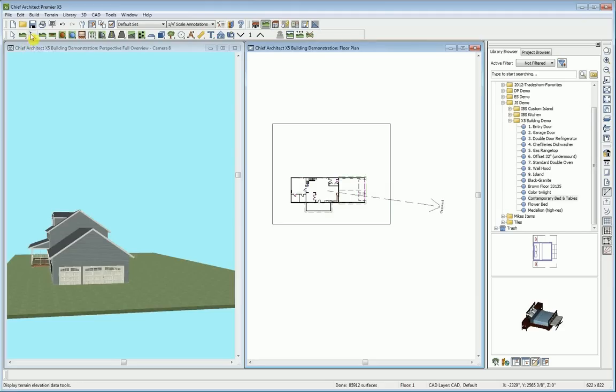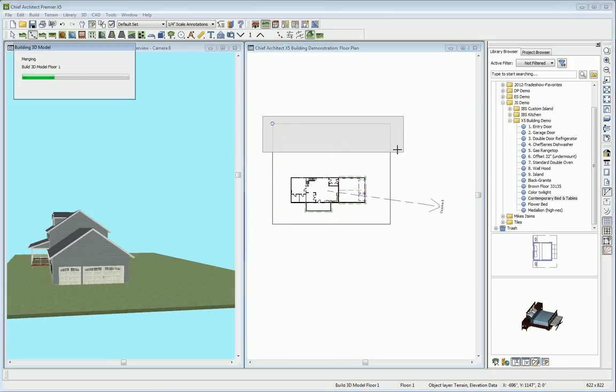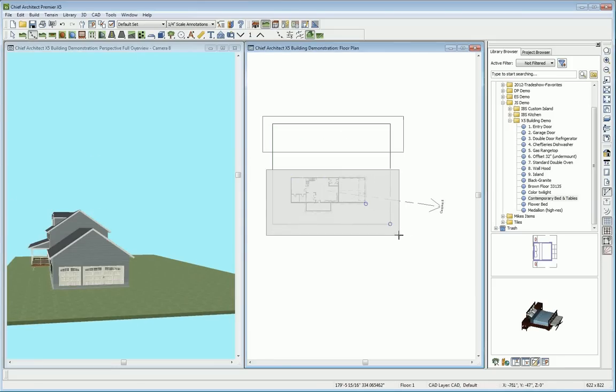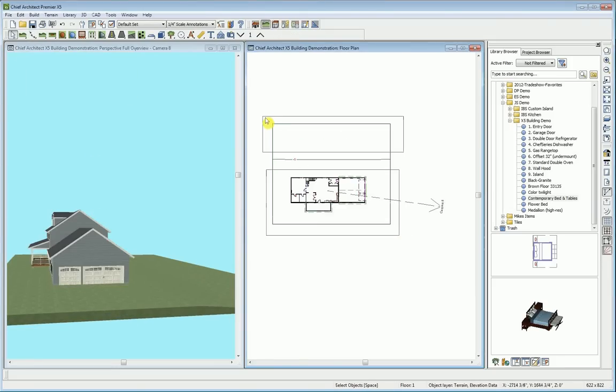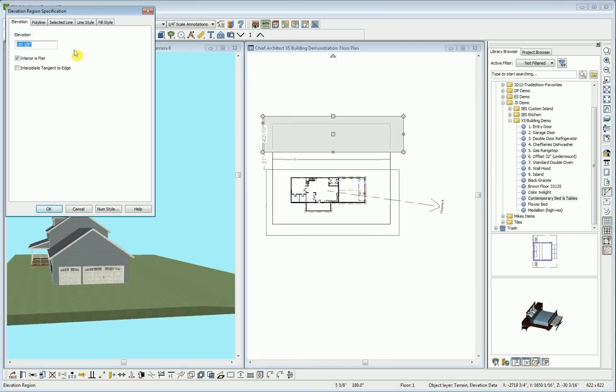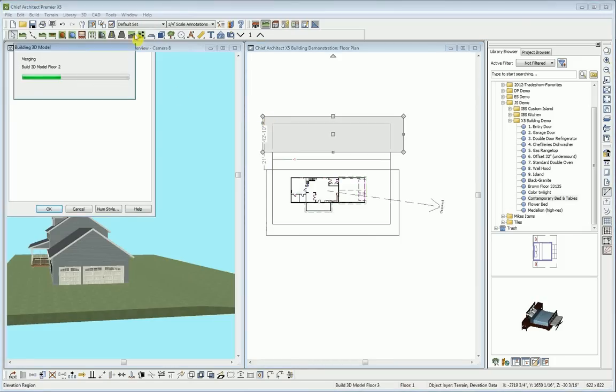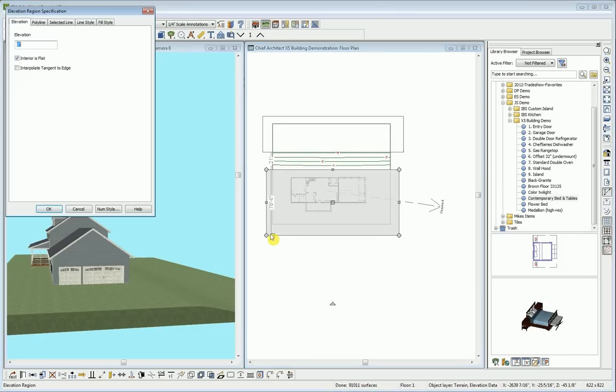So within our terrain tools, we have elevation tools, decks and fencing, driveways, sidewalks. We'll move into our elevation tools where we can add elevation points and lines. I'll go ahead and just add 2 elevation regions. So I'll just click and drag over 2 different regions. And I'll double click on this back area and make it -50 feet. We can open up this area and let's see. We'll go ahead and just leave that one at 0.